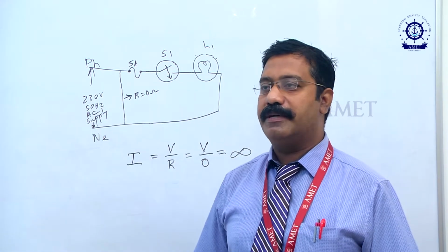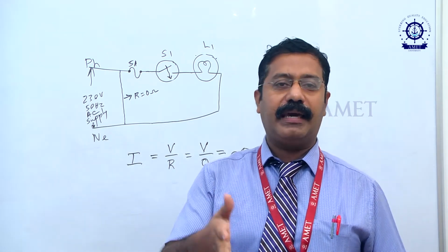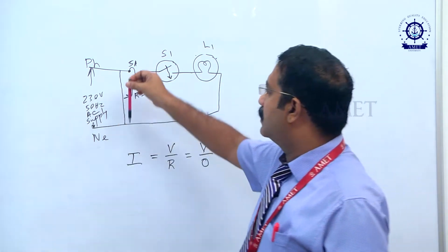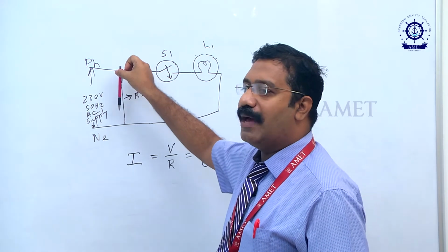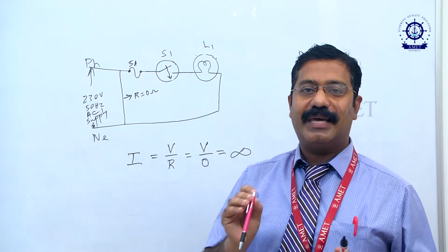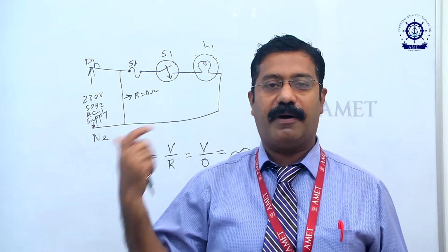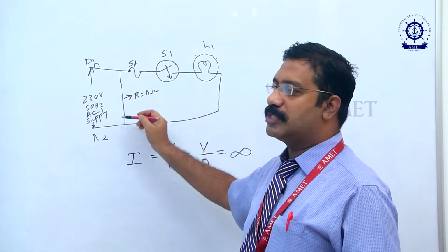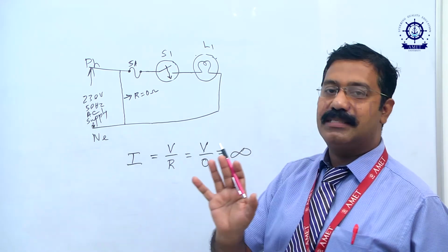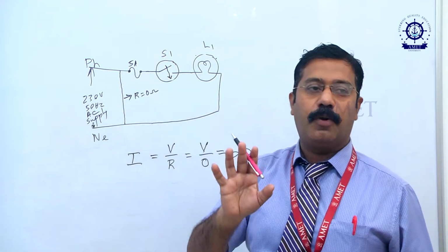Wherever we develop a circuit, if a short circuit happens, it's not that we are deliberately making it. For example, if there is a metal part lying over here, or a bare wire which connects phase and neutral, it makes a short circuit. In that situation, my load or appliances will not get the actual power. Because of this short circuit, my current value will be very high, which will damage the circuit. If you have equipment like a fuse, then that fuse will blow out.